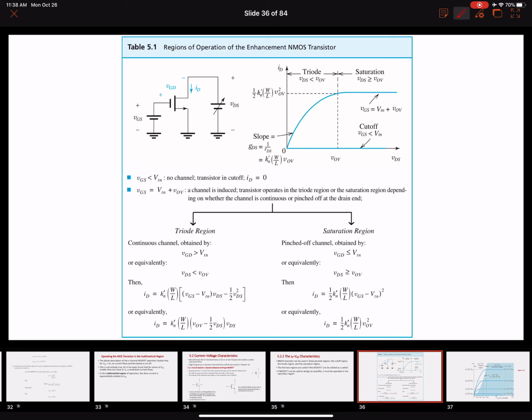So let's very quickly go through this slide so you know all the details there. Here's the circuit symbol. There is no indication of the terminal, so we know that this is a drain. We know that the arrowhead is on the source, and the remaining one is a drain. Here's the drain current from the drain to the source. Looking at the arrowhead, I know it's an NMOS.